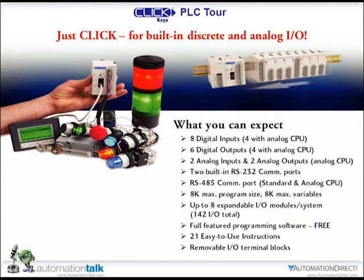Let me go through a little bit more, and then like I said, I broke these down in some better slides, but this is sort of an overview. Like I said, you've got the digital in, digital out. You've got the analog. It has some digital in, digital out with analog inputs and outputs on it as well. 2 built-in RS-232 communications ports on all of them, and then on the one I've got in my hand here, the standard, and then the analog, you have the additional RS-485 communications ports. And you can see some of the other features that we've got on there as well.